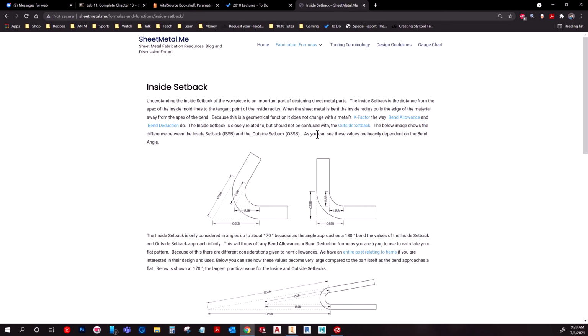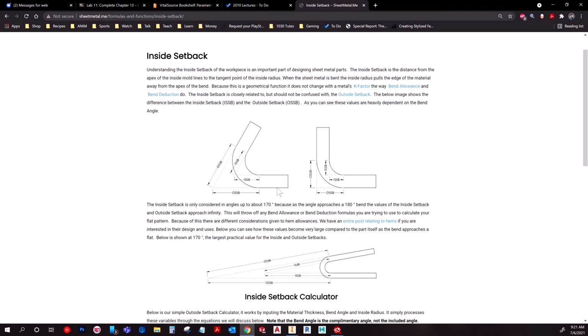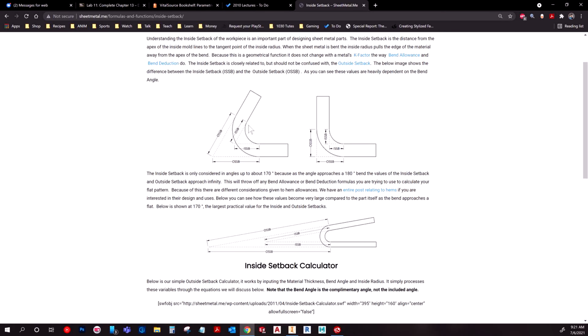These two tabs, this and outside, are pretty much the same, with descriptions for each listed. I would suggest going through and reading all of this. But it's really cool to see a metaphoric projection of what this looks like. So if you were to draw a non-sheet metal part, you would have everything come to this point right here, with sharp edges. But when you're making sheet metal, it folds, so you end up losing that sharp end. You still have those technically, like even when you're drawing, you'll have a point there whenever you're making your fillets and whatnot if you're doing it on a sketch.